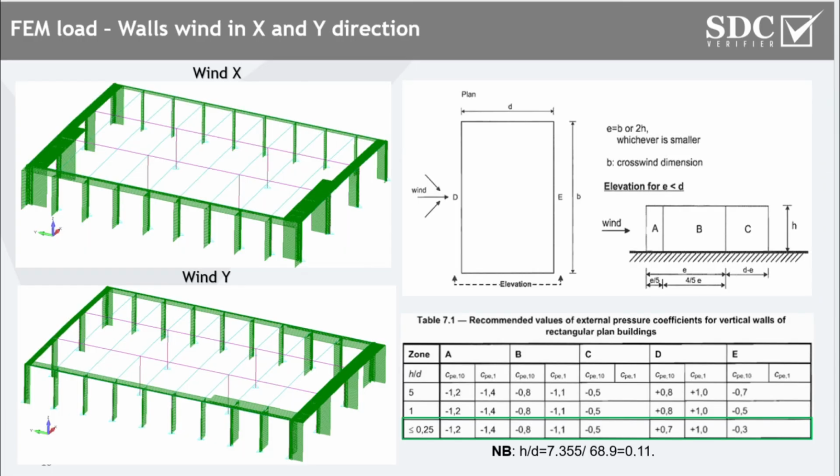Okay, next one, this is the second wind load, and this load represents the impact on the roof, while the wind impact on the walls is also interesting, because we do not apply wind only to the front surface. We should apply it to all of them, and it is also shown that our side surface is split into sections A, B, C, and we also need to apply the wind load on the back surface.